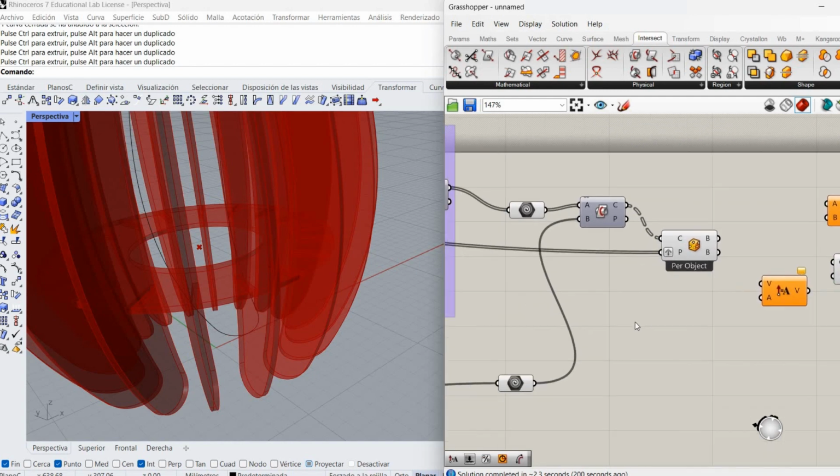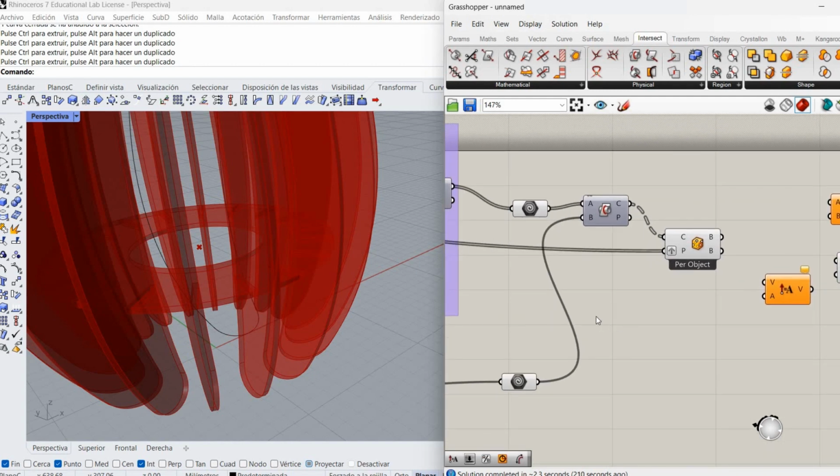Then those vectors, to create a vector, I can use a face as I showed you before, or I can use, for instance, a line. If I can get a line where those objects are being intersected, then I can move those boxes along this line and then make the volume difference.